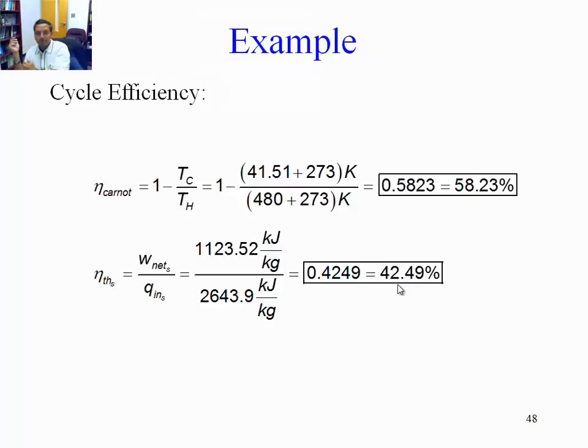Check your power bill every month, and you'll see that the cost of electricity, besides the base cost, is maybe, I don't know, depending on the area and the time of the day, maybe 20 cents per kilowatt hour. So you have 240,000 kilowatts, you multiply by hours, and you multiply by 20 cents a kilowatt hour, and you'll see what kind of savings you get on a daily basis, on a monthly basis, or on a yearly basis. And you'll see that a 2% increase in efficiency is huge. It's something that is not only worth it, it is absolutely necessary.